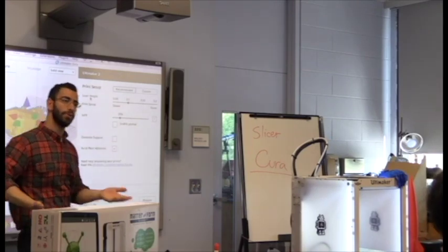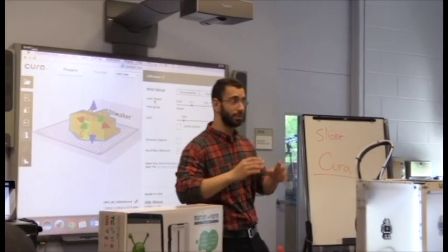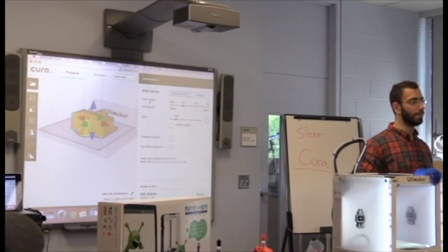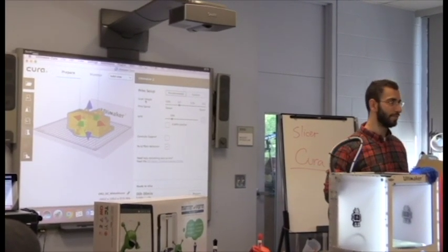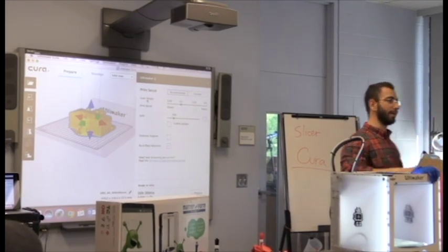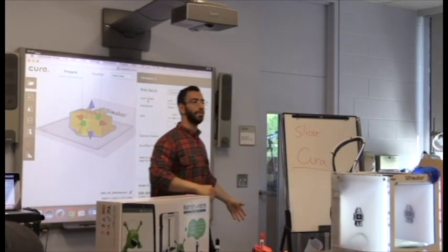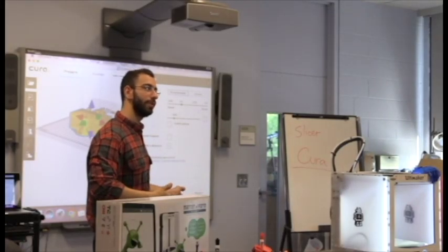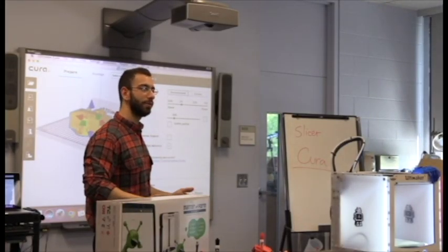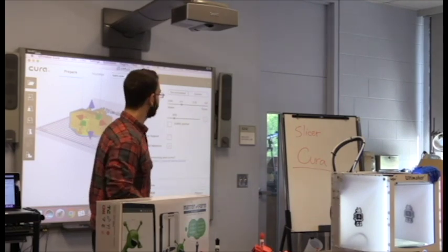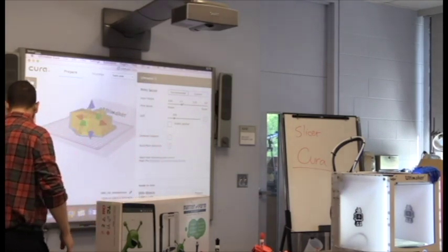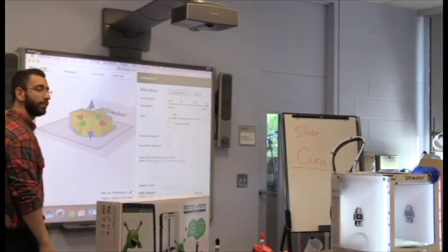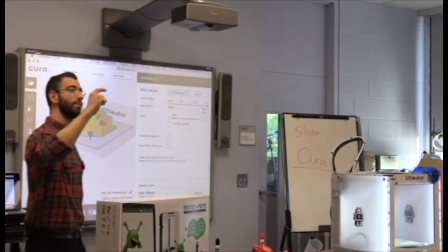Usually, printers can only go down to a specific layer height. Usually, it's about 50 to 200 microns. Microns, again, 200 microns will be 0.2 millimeters. That's what you're going to be working with, usually whenever you just want to rapid prototype stuff. You'll just roll this over. That'd be 0.2 millimeters. It says faster prints because each layer is so much thicker.